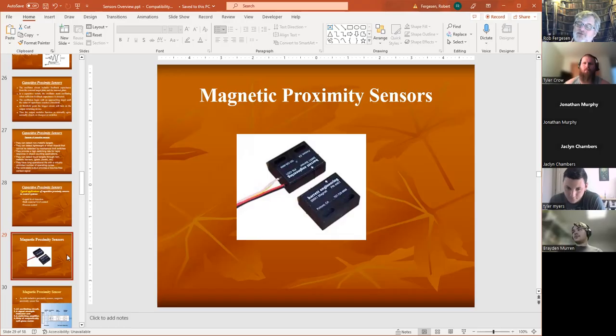Now, there are some sensors out there called reed switches, which are really lightweight switches embedded in a bit of plastic. So when I bring a magnet over near that switch, that magnetic field of that magnet causes the mechanical switch to click closed. And those are very inexpensive, and those are used all the time as sort of door switches or cover switches. So if you pop a cover open, it'll turn off the machine. If you pop a door open, it'll set off an alarm.